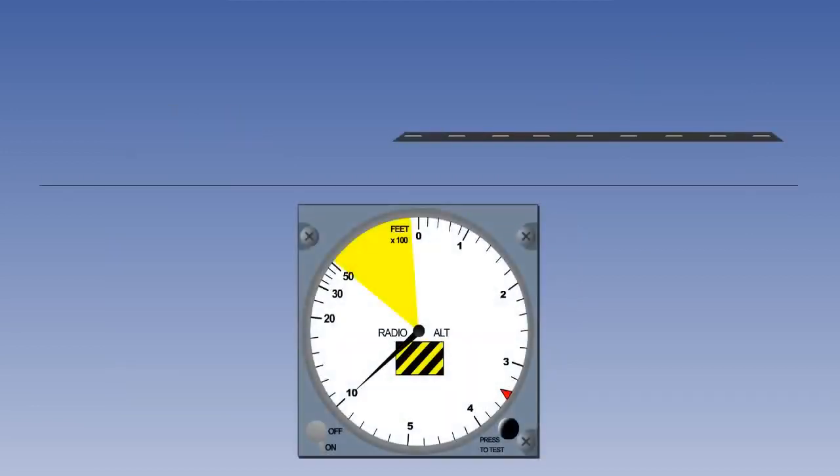Mode 6A operates between 50 and 1,000 feet and provides the crew with an aural warning if the aeroplane descends below the minimum decision height as set on the captain's radio altimeter. The aural alert "minimums" sounds only once and will be rearmed when the radio altitude becomes greater than that selected. "Minimums."